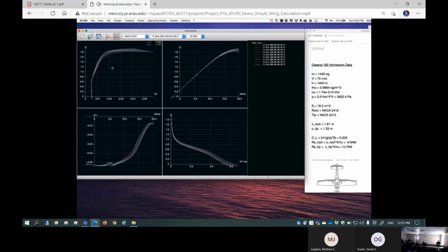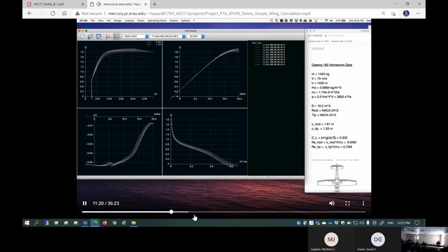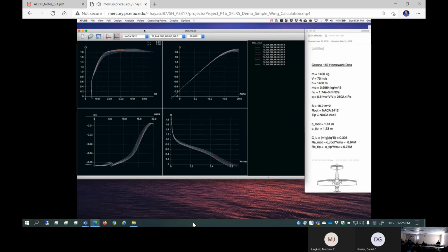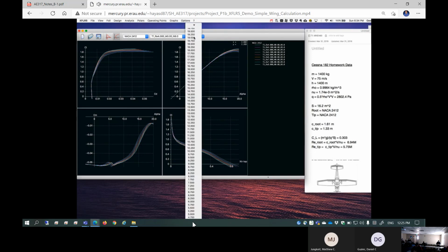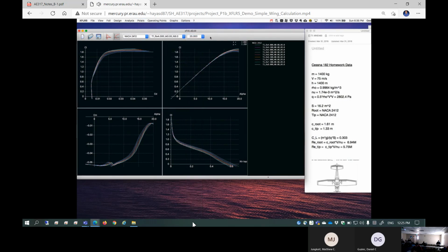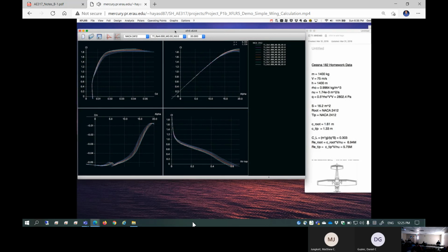I won't go through all these because we've talked a lot about 2D sections, but you can see here's our typical CL/CD XFoil plot and transition plot, and the moment curve here, which is generally plotted in traditional XFoil on top of the CL alpha curve. So that's the performance data done. If you want, you can plot just one of these. You go to Polars, and there's current polar, show only certain operating points. So you can filter down if you have too much data. But in this case, we're not really interested in investigating the polars. We're going to move on to the 3D part.